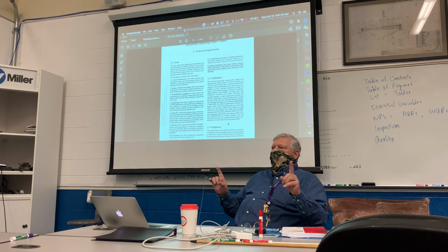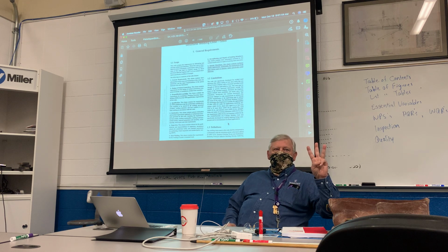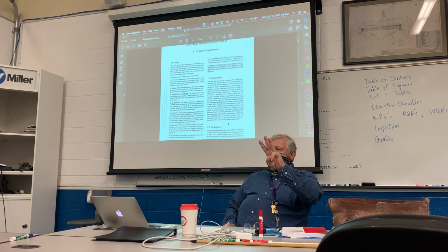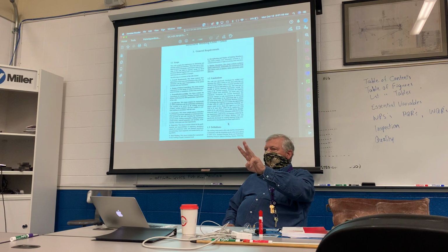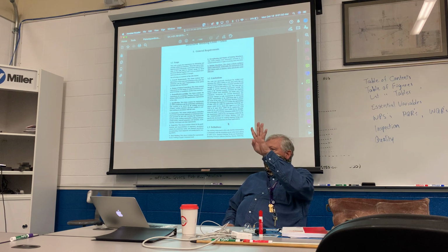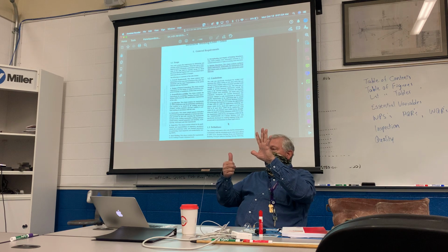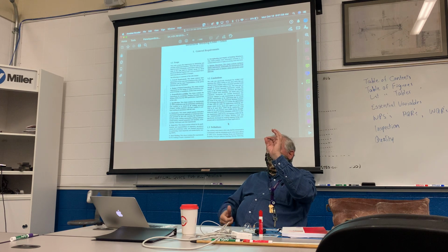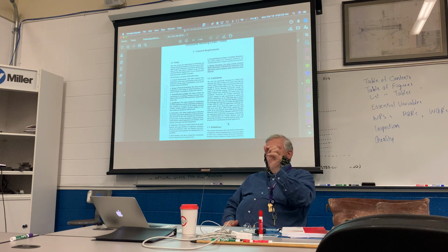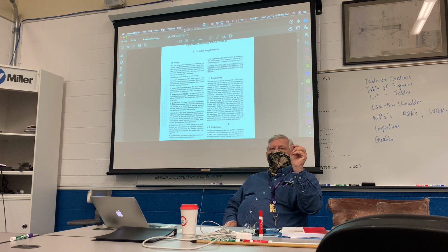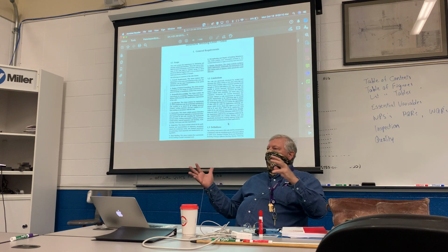Every number starts at 3. Number 3 rebar is 3/8 thick. Number 4 is 4/8 thick. Number 6 is 6/8 thick. They're all numbers of how many eighths thick it is. But instead of it being just 8, if it has a W in front of it, W8, that's weldable 8.